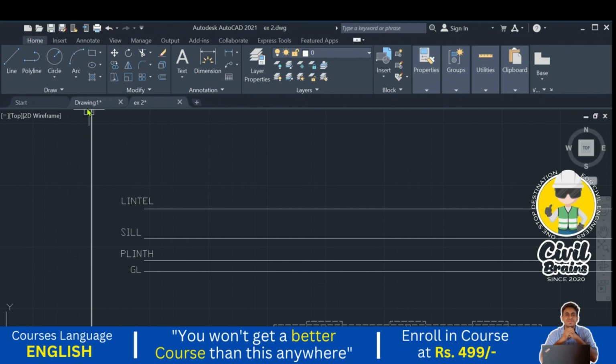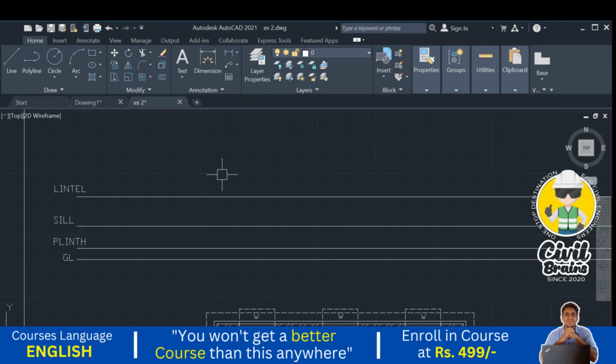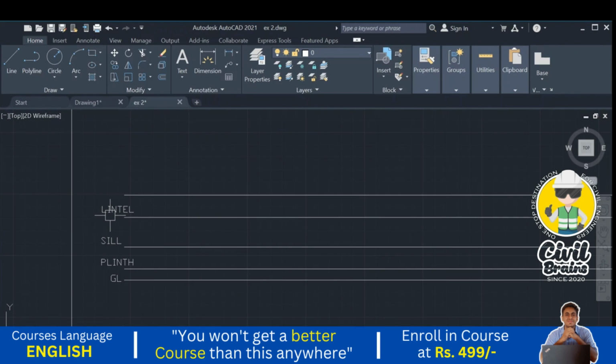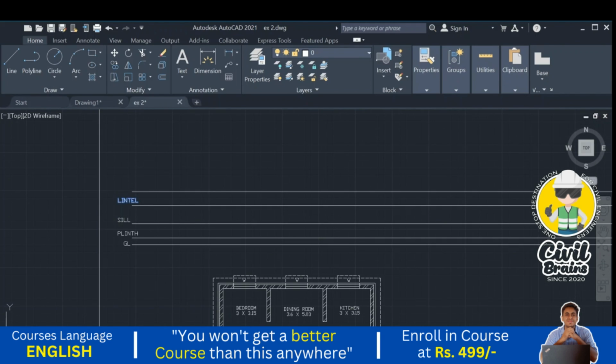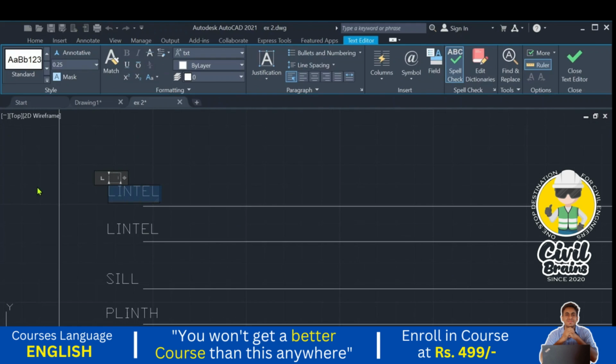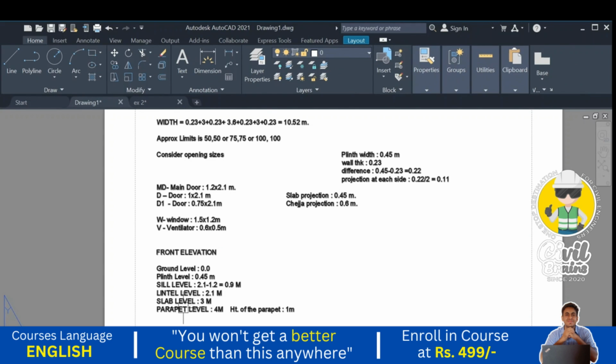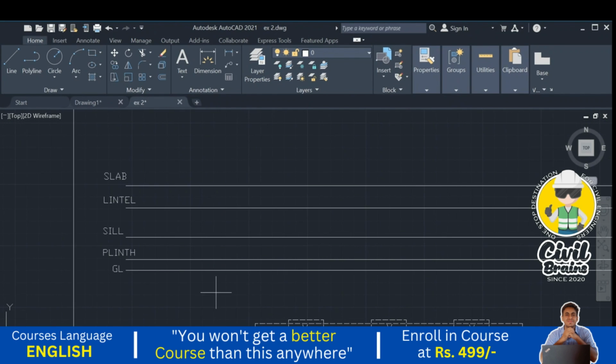Next, slab. Next one is slab level, that is 3 meter. That is from the plinth level only, offset 3 meter, press enter. I just give you 3 meter, copy, slab. Next, parapet level 4 meter, that is also from the plinth only. So every distance we are giving from the plinth only.